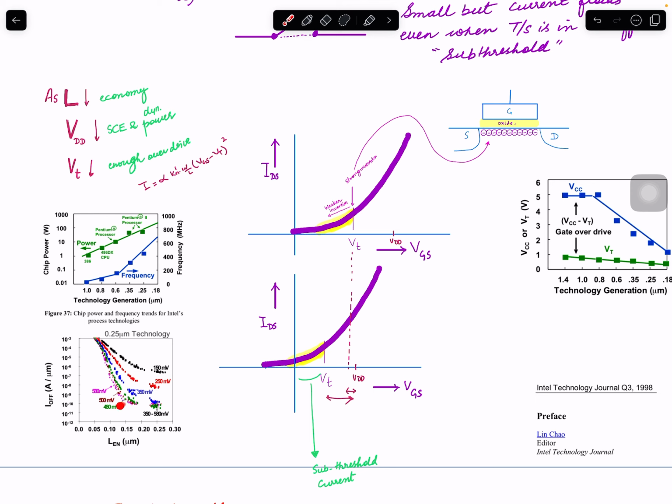These are different threshold voltages and the off current, and you can see that when you drop the threshold voltage to this 150 millivolt as opposed to, let's say, 500 millivolt, the amount of off current is much higher. So that's the problem. By the way, I forgot to mention, this is that gap between VGS and VT I was mentioning. But anyway, I hope you understood this concept. So that's the problem with lowering the VT. It helps performance. Performance is good, but the power is not good.